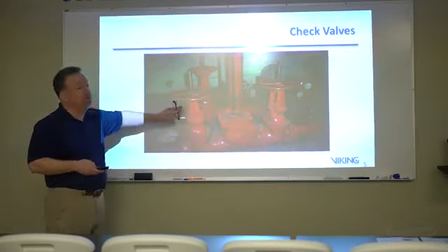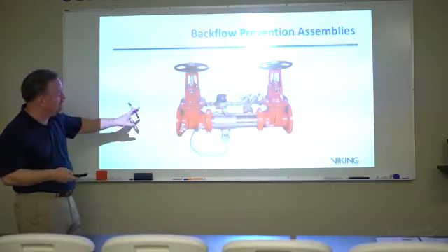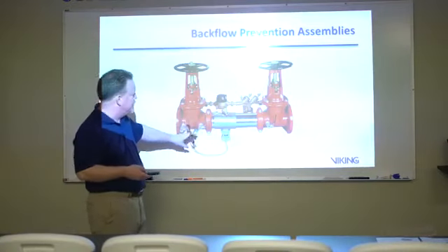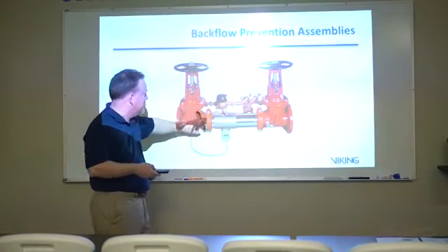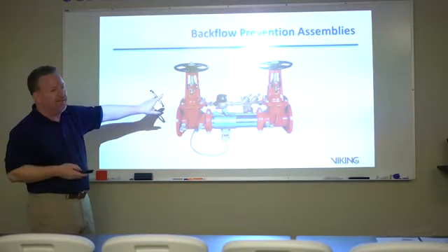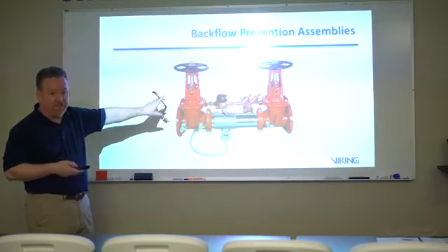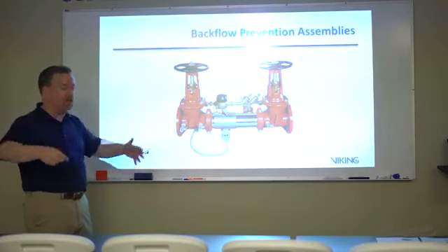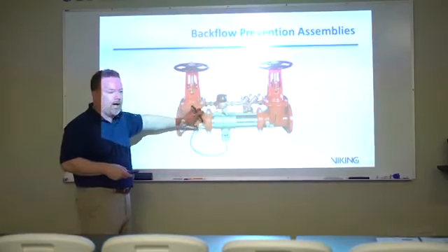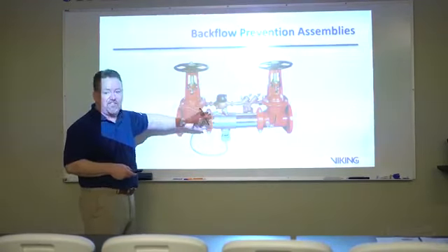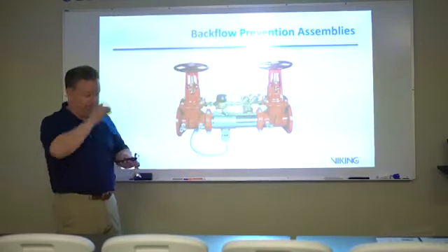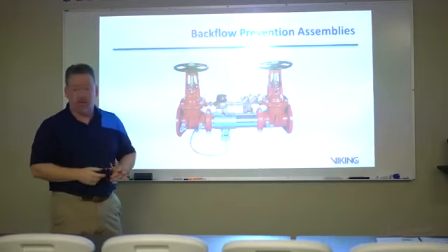The big challenge here with backflow prevention devices, number one, this is a reduced pressure zone backflow prevention device, but primarily the biggest challenge is if you're retrofitting them on a system, they have a pretty significant friction loss in and of themselves. So if you've got a system that requires 15 psi at the most remote, and you put this thing on, and this thing takes 15 psi away from the system, what do you got at your most remote sprinkler? 0. So what do you wind up doing?